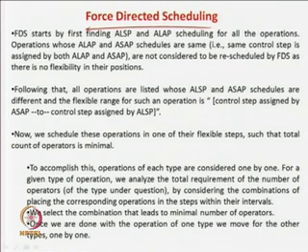So, what do you do in force directed scheduling? In the first step it will go for the as soon as possible schedule once and the as late as possible schedule once. You have to see that in the last case also we went for as soon as possible, then as late as possible, and then tried to find out which part of the circuit is better. That is actually a very fuzzy way of stating something, finding out which part of the circuit or which sub part of the circuit is better. Here, we are going to make very crisp steps of the algorithm.